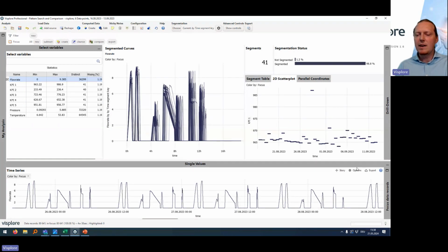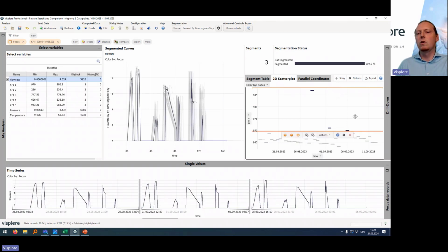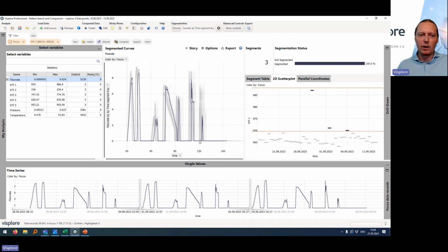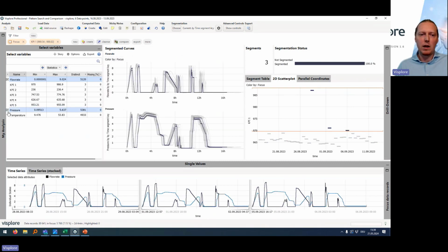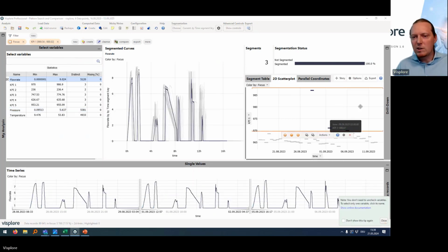And we could correlate this KPI now with the flow rate by saying, what were those where the KPI was off the normal? How did the batches look like, right? A common question for process engineers here. So let's select vertically everything above a certain threshold. And you would see these high KPIs are achieved for some batches that look like this. And we could also take a look, for example, what the pressures were doing at the time and so on. Okay, so this is the simple correlation between the quality and the process data.